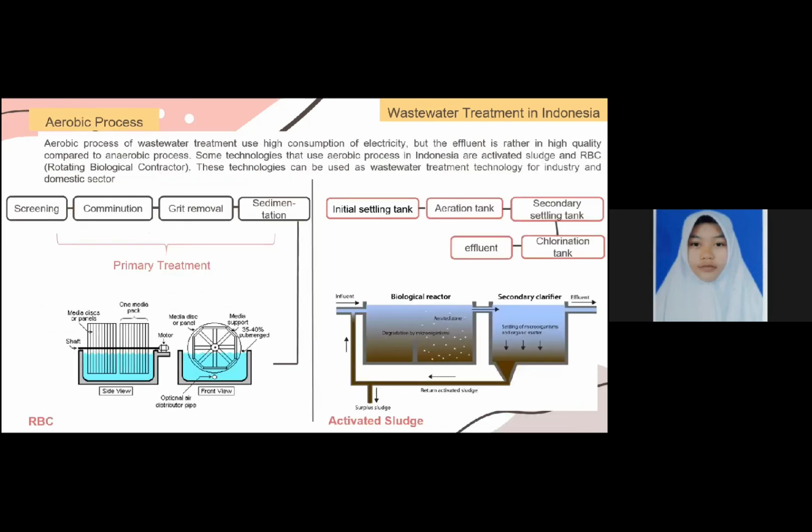On the other hand, the aerobic process of wastewater treatment uses high consumption of electricity, and the effluent is of rather high quality compared to the anaerobic process. Some technologies that use the aerobic process in Indonesia are activated sludge and RBC. These technologies can be used for wastewater treatment in industry and the domestic sector.